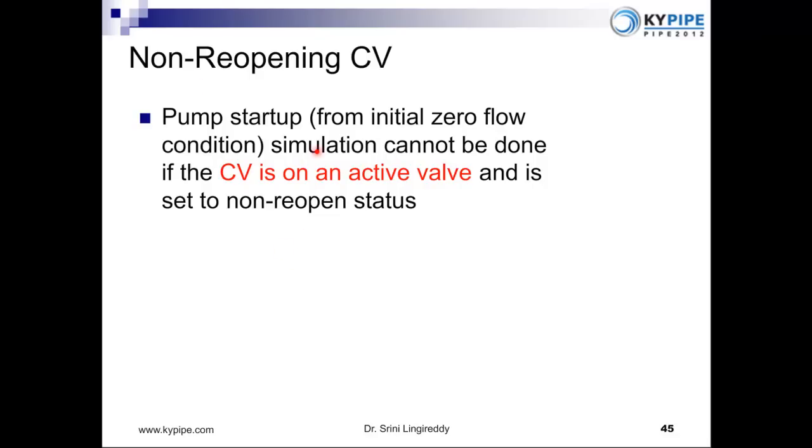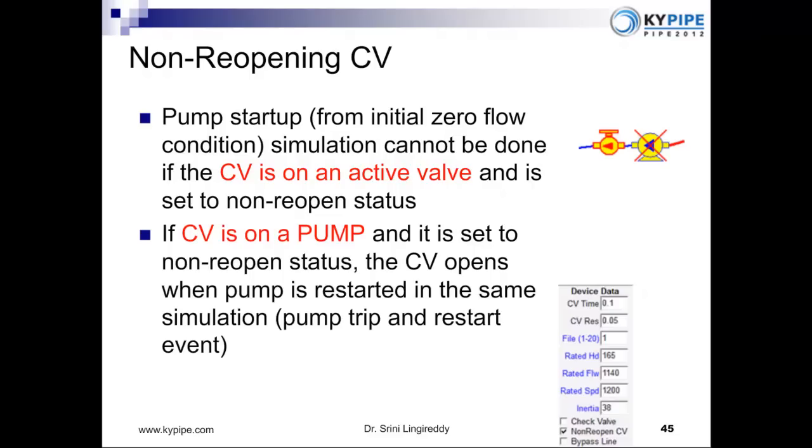And one caution here: when you have a non-reopening check valve at the pump startup, it may remain closed and will not open. Sometimes that can be a problem, because many users think the check valve is not operating. But if you have it checked as non-reopening, once it is closed, it's not going to open. Now we did make a small change to this non-reopening check valve.